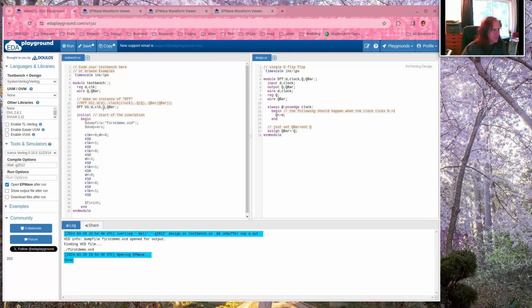So this business of naming the connection something different, specifying what port they're being connected to by name, that's useful when you have a module with, like, 20 different inputs to it, so we don't have to remember what the 17th input is supposed to be. But for simpler modules with just a few input and output ports, we can just instantiate it like this. That makes life a little simpler.